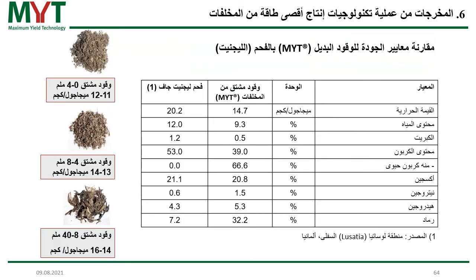So let's have a small comparison of the quality parameters of the MYT substitute fuel with coal, but not hard coal, but lignite coal. You see a small difference in the calorific value, and water content is nearly the same. In sulfur, the MYT RDF is quite low, but here you cannot take these numbers and apply them to everything, because it is important where the waste comes from, where it originates from.